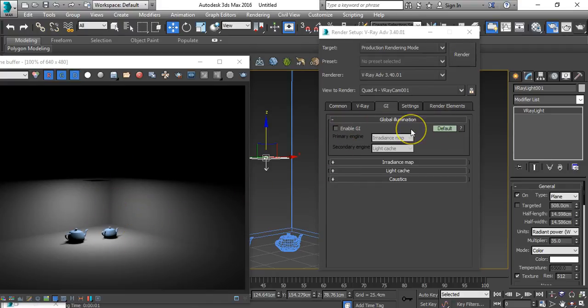Now what is global illumination is like, it will illuminate your room globally, in simple language. If you see this light, this is giving the direct light here, but there is no indirect light. When you switch on your light, the light throws photons, and those photons go to your wall and then bounce back to other walls, and then bounce back to other wall, floor, ceiling, everywhere, and the light generates. And it is an endless process. So that's why we can see the light, right?